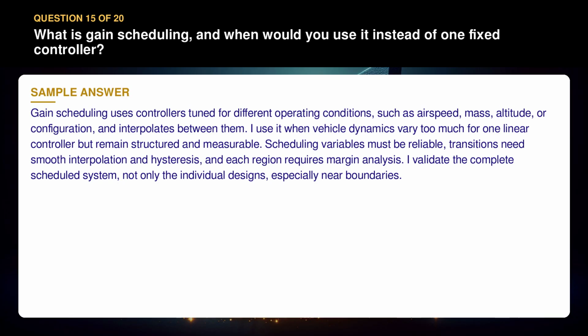Scheduling variables must be reliable, transitions need smooth interpolation and hysteresis, and each region requires margin analysis. I validate the complete scheduled system, not only the individual designs, especially near boundaries.